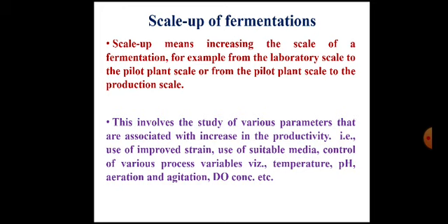Scale up of fermentations involves the study of various parameters that are associated with an increase in productivity. That means the use of improved strain, the use of suitable media, and control of various process variables like temperature, pH, aeration and agitation, dissolved oxygen concentration, shear conditions, and dissolved CO2 concentration. All these parameters are never going to remain constant when you go from small scale to higher scale.